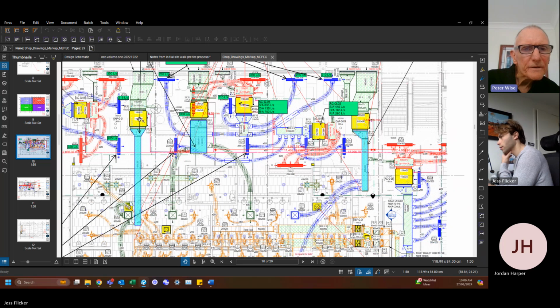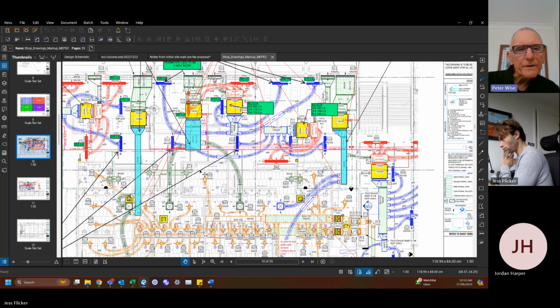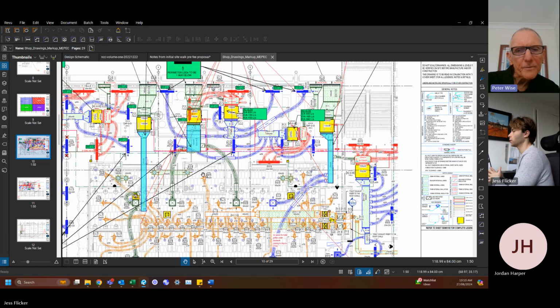Well, that might be a special. What sort of system is it? VRF, is it? Okay. With the main manufacturers like Mitsubishi and Daikin and probably some of the others, you can get special fan coil units designed to just operate on fresh air or outside air. The standard units won't function on 100% outside air, but these special units will. And they just deliver a lower airflow rate, and they can perform okay. Okay, so they're not actually ERVs, those units.